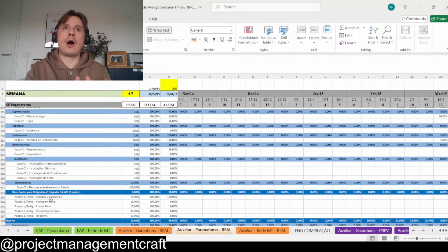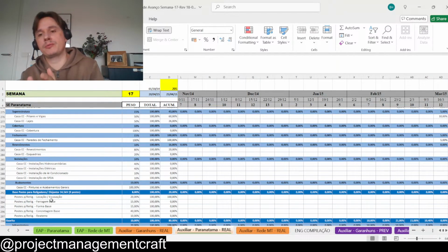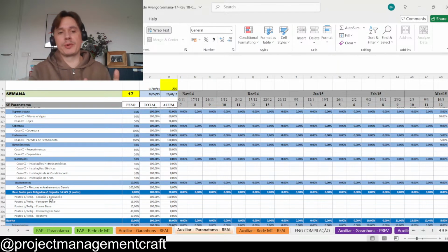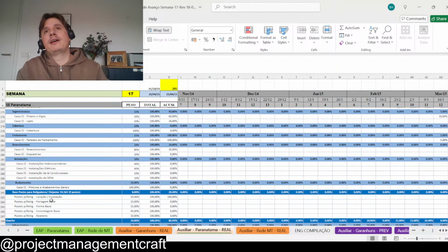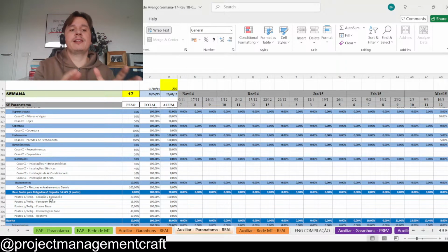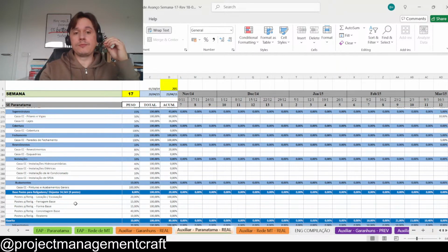Okay, what's the productivity that needs to happen per week there to make sure we reach that? And based on that, you can say, oh, this week we did not meet our productivity target there. I mentioned that for the concrete, we should have done 100 or 200 cubic meters per week, and we did only 150. Okay, do we have the possibility to work one extra day, like on Saturday with the team? Then we plan one extra day so we can recover this type of delay. So you can manage this in a proper way. And because this is done on a weekly basis, it gives you very good tracking.